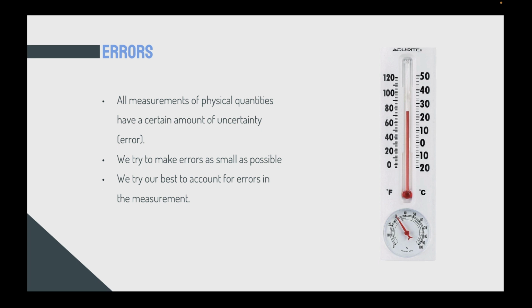When you open the sensor box, you'll find a calibration sheet showing when it was calibrated. What is the 0 for that sensor? Some sensors start with the number 2 and the rest is the real values. Some sensors start with 0 as any other accurate sensor. It all depends on accuracy and the calibration method used. So you got to keep that in mind.